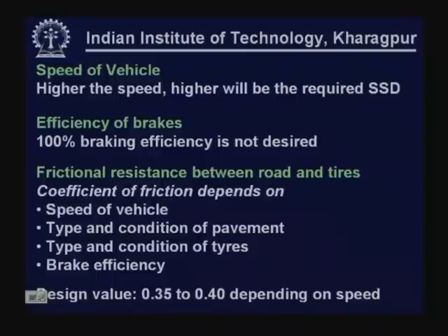Now, it also depends on the speed of the vehicle. Obviously, the higher the speed, the higher will be the required SSD, because it will take a longer time for the vehicle to stop once the speed is higher.